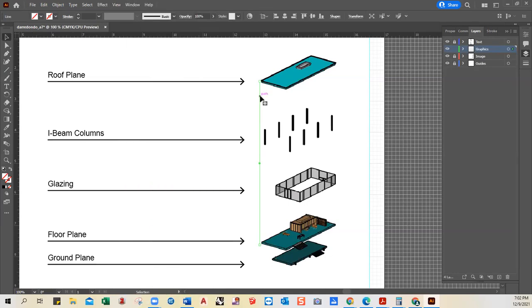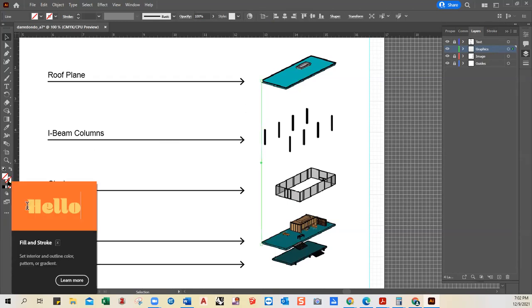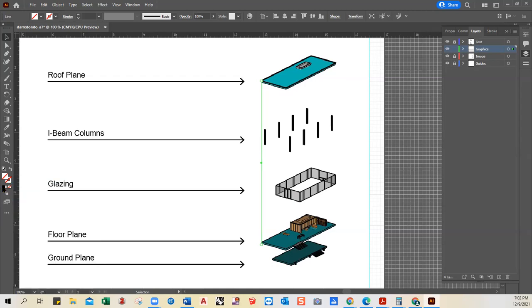And then I'm going to use my arrowheads to move it over. And then as of right now, notice it disappeared. Why? Because by default, it went back to no color. But notice how I remember what color swatches I used earlier. So I can click on that black, and then I could switch instead of the fill, make it the stroke by clicking on these two little arrowheads here. So there's one. I can hold down Alt, and then I can left click, hold down Alt, left click to add